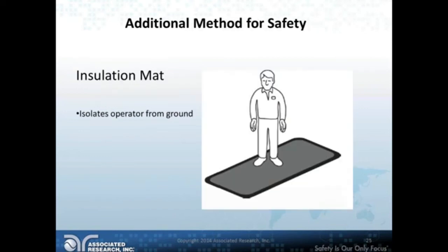And then, of course, as you saw in the previous pictures, insulation mats. I have two of them here in my lab, and when I'm running tests, I'm standing on them the whole time. It's just a really easy way to isolate you from ground and a simple way to keep your operators safe.